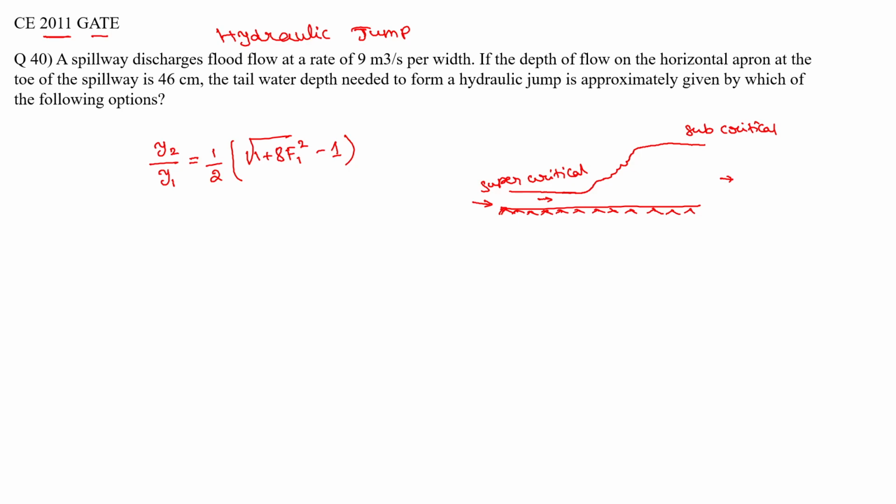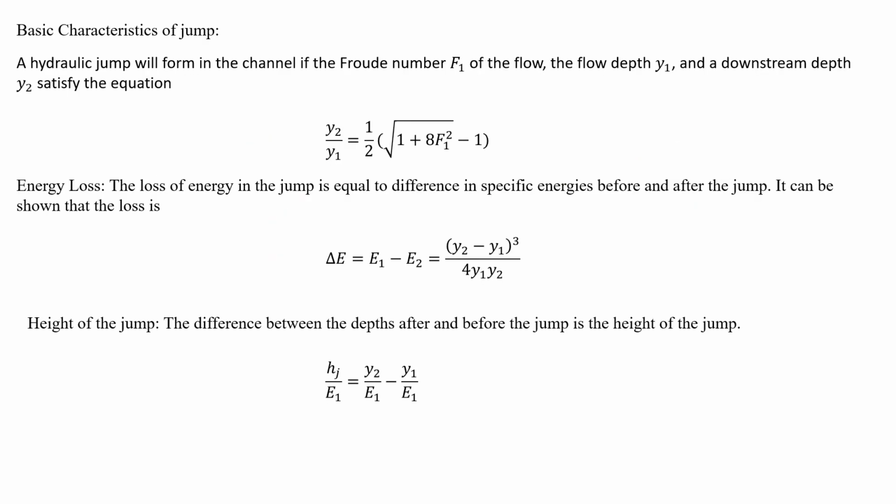And another equation, what? Energy loss equation. Okay, (y1 minus y2) whole cube divided by 4 y1 y2. I hope I'm correct. Anyway, in the next slides I have shown. Yeah, correct. So these are the basic characteristics of the jump we discussed in the previous session.